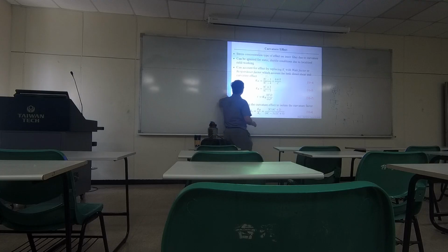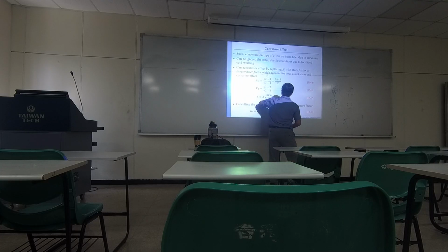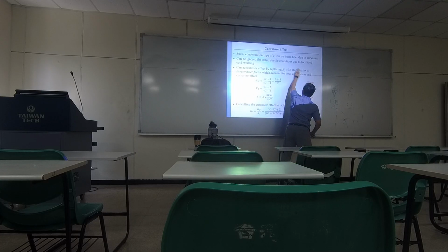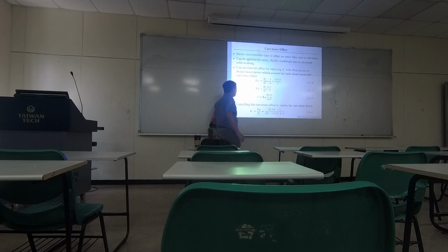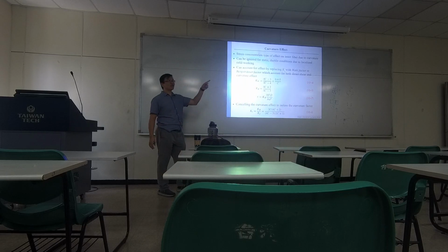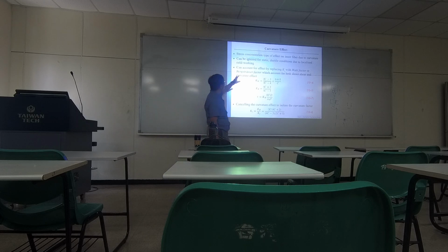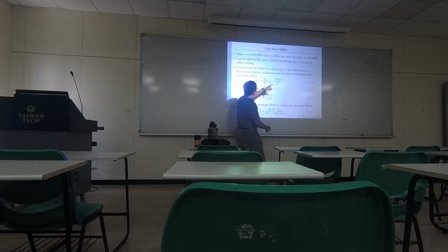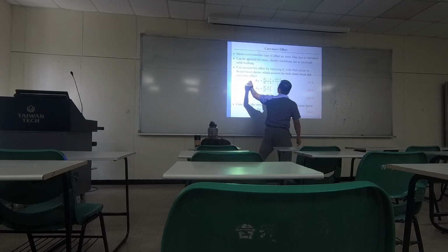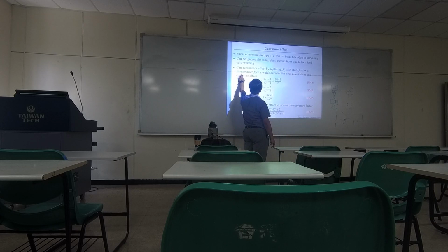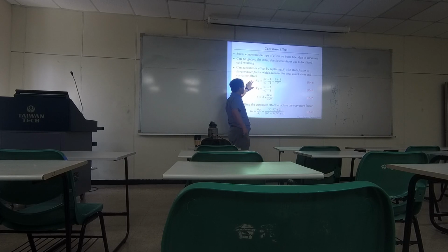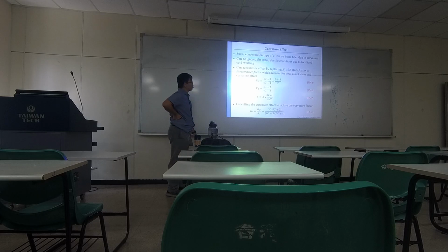These are the models to update the coefficient that I just mentioned, because they realized if you directly use 2C plus 1 over 2C, it's not accurate enough. So there are researchers trying to figure out, like Wahl and Bergsträsser, they did some research and realized you can correct the K value in a certain way. Okay, so they are based on different research.